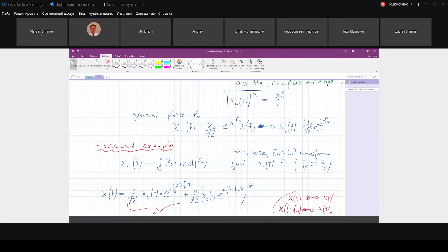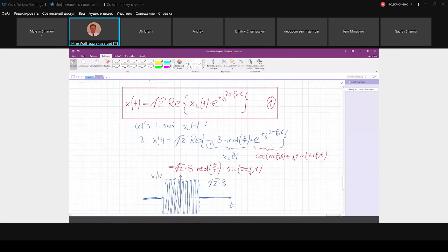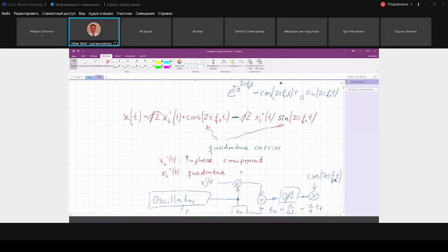As I said, in the next lecture, I show you a practical schematic to do this. I closed the presentation. The thing is, if you do this analog, you can say, I have this quadrature down conversion and I obtain the real part of this complex signal, which we denote as the in-phase component. So I just obtain the in-phase component.